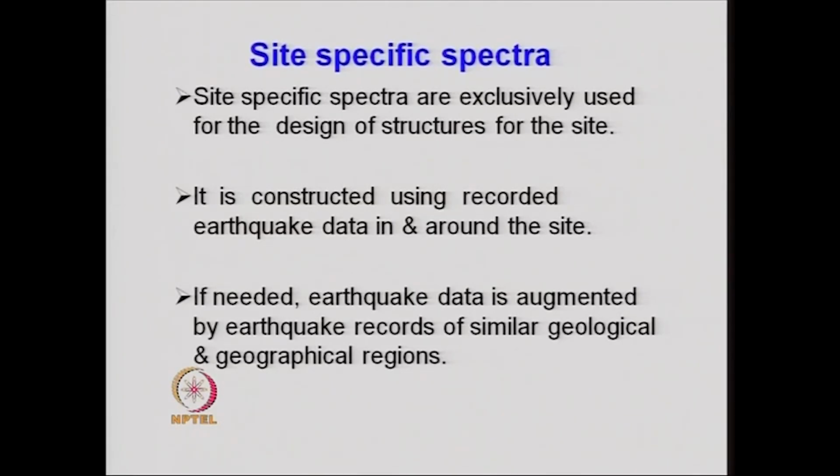Now for that, what we do is collect as many earthquake data as possible for that particular site, that is in and around that site. Sometimes if the collected data is not sufficient, then we augment the earthquake data by collecting data for similar geographical and geological regions.